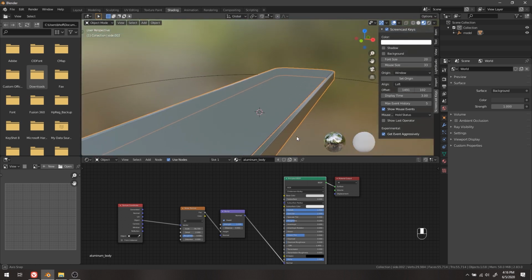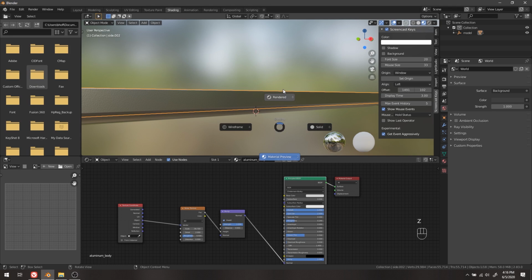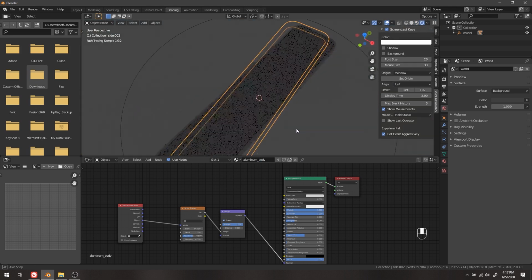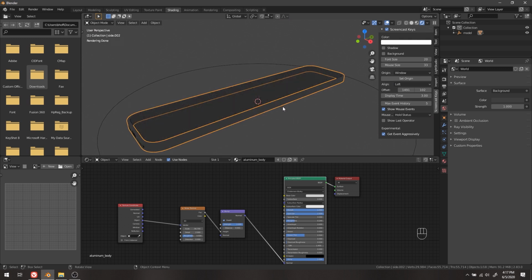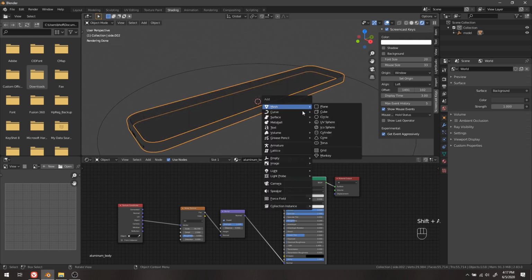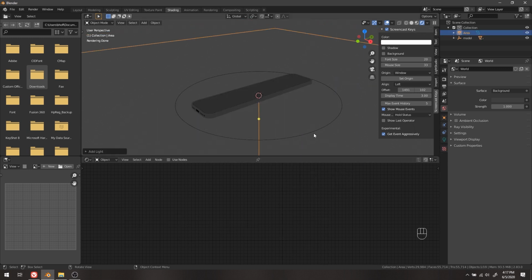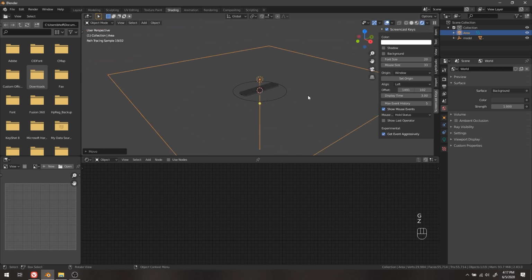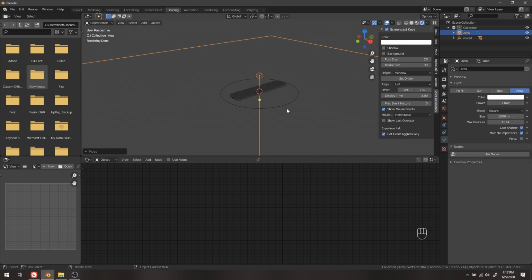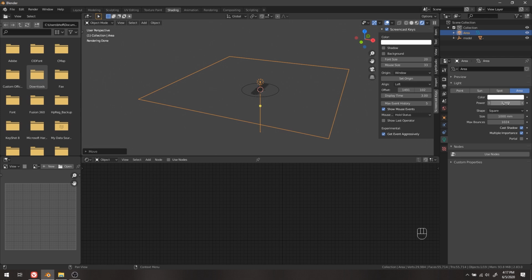Now, like I said, this is the material preview, sort of like the fast render. If we go over to render by hitting Z, we'll notice that it's gray, and that's because there's no lights in the scene. So if we hit Shift A up here and select a light, I'm going to recommend area. And again, we can dive into what each of those light options are at a later date. We're going to add an area light. So that's just one massive square that's all emissive. Right now the power is a little bit low. So just type in 1 there and it's going to bump it to 1 watt. Blender recently changed this over from an arbitrary number to watts.